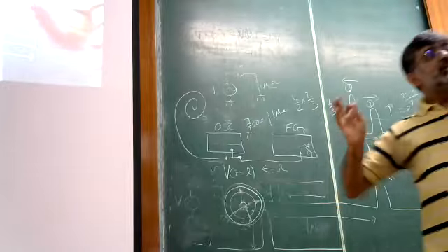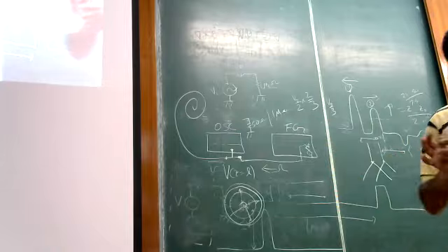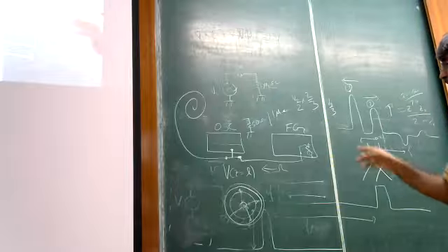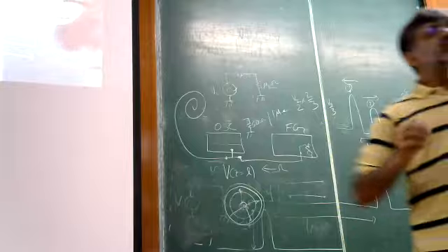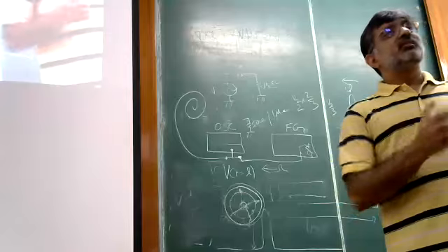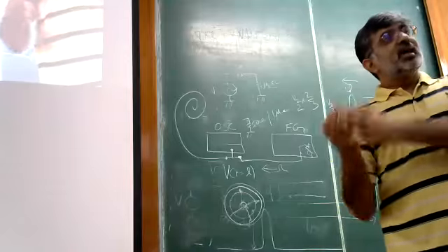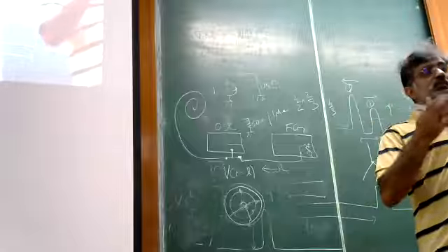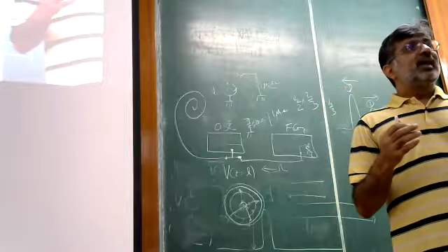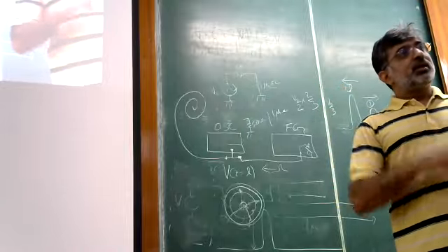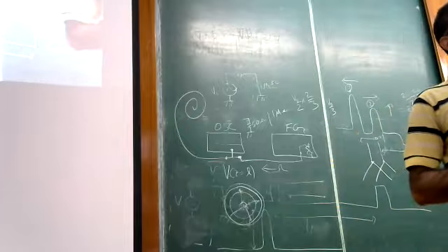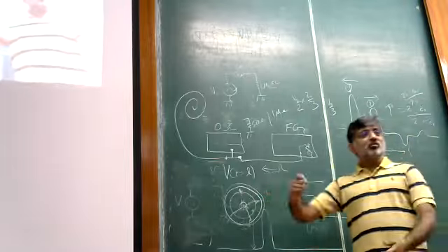So that's why the waves which propagate here, and I think in the next class we will look at this from the electromagnetic point of view in detail, this is called a transverse electromagnetic wave. So unlike just a transverse electric wave or a transverse magnetic wave, maybe you might have heard these terms in your electromagnetic classes, this is called transverse electric magnetic wave. And the electric field is perpendicular to the magnetic field, and both are perpendicular to the direction of propagation, because the energy is flowing in and out of this plane.